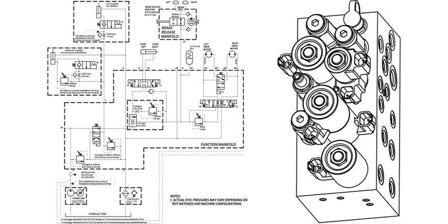Shown here are the hydraulic schematic and function manifold used on the GS 2032, 2632, 3232, 2046, 2646, and 3246 models. The schematic and function manifold are very similar to that shown on the previous page for the smaller machines. On this schematic you'll see an additional lift cylinder with an incorporated relief valve, used during auxiliary lowering. Dashed lines are shown above the pump, continuing to a second page showing the outrigger system used solely on the GS 3232. The other difference is the addition of a 2-position, 4-way solenoid-operated valve, used to switch between high and low drive on all of these larger models.